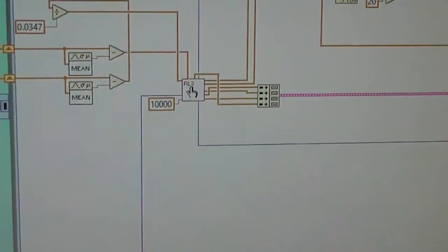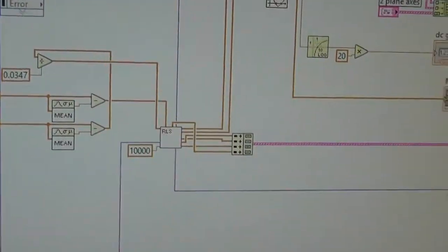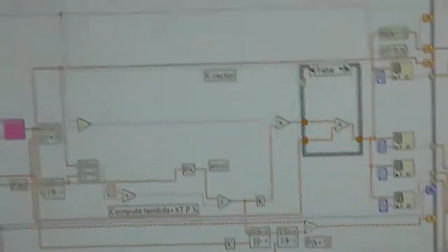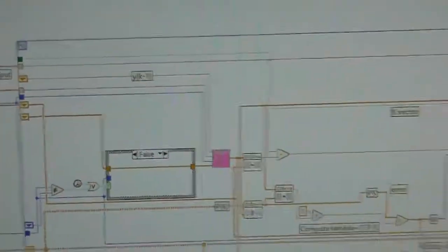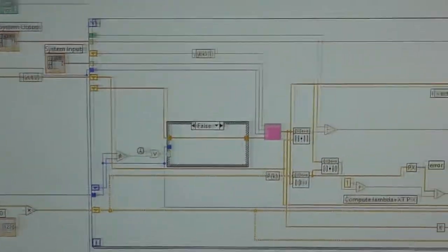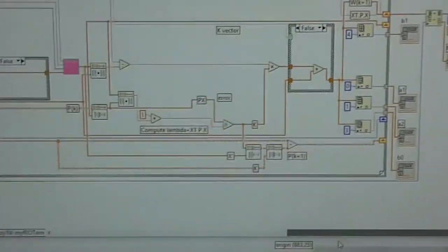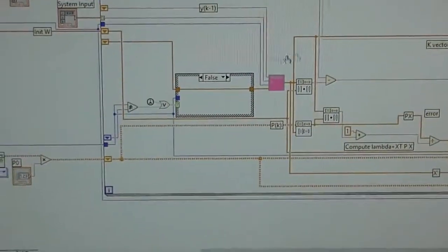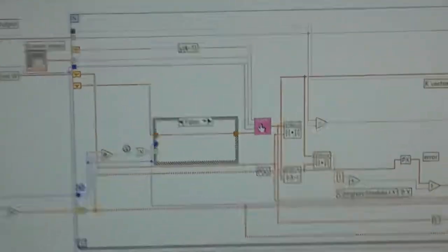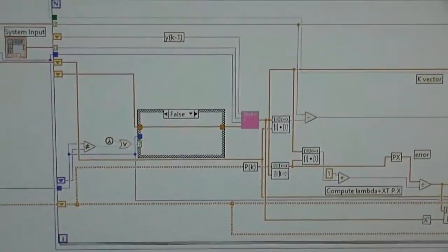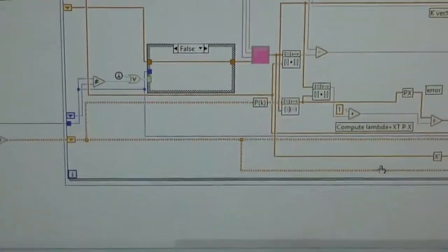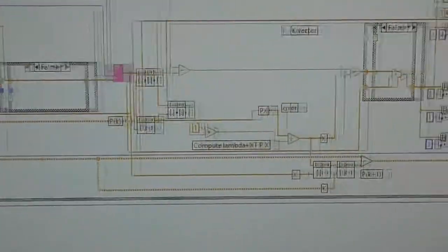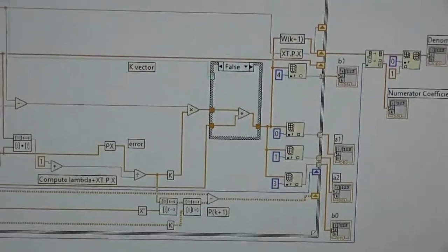And here's the recursive-least-squares algorithm. It's over here. I wrote this a long time ago, but LabView's also got its own one in a sort of toolkit, but this is my one, doing all the things that are in the equations. It's a for loop that goes round whatever many times. This is the regression vector that shuffles the regression vector. These are matrix multiplications and matrix times vectors and so on and so forth.